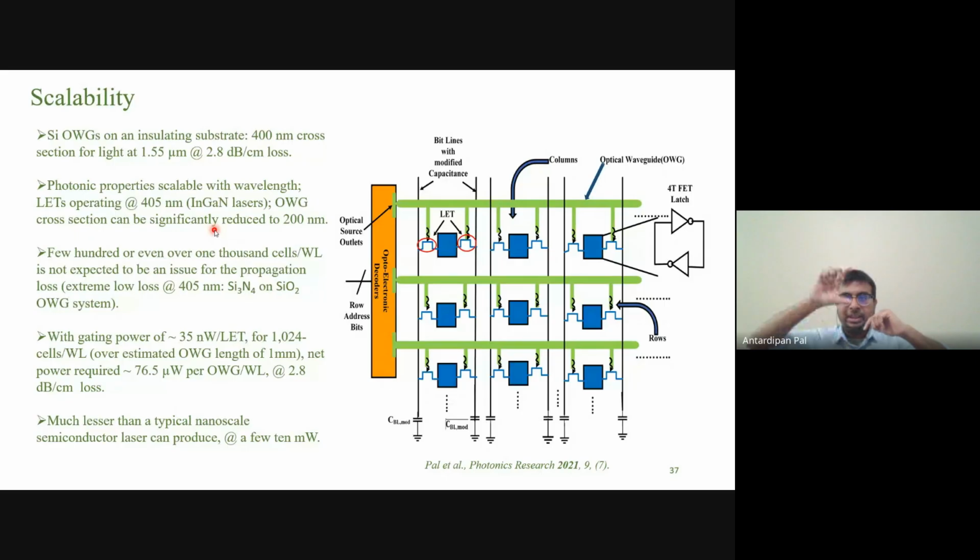You know the band gap, right? The Eg. So E equals hc over lambda, so lambda is hc over Eg. That's the band gap. So you just do some band gap engineering to generate blue light. The most suitable is indium gallium nitride. It's a hybrid laser, a ternary semiconductor.